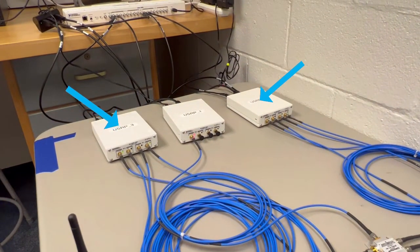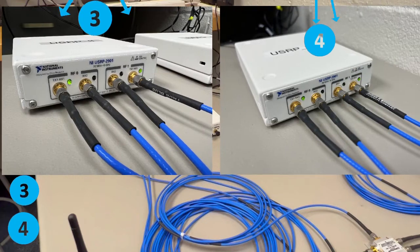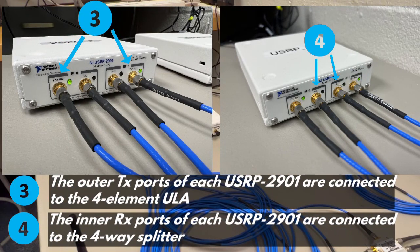The outer USRPs are responsible for receiving signals at the ULA as well as the 4-way splitter. The outer RX ports marked by the green indicator light are connected to the ULA, while the inner RX ports are connected to the 4-way splitter.